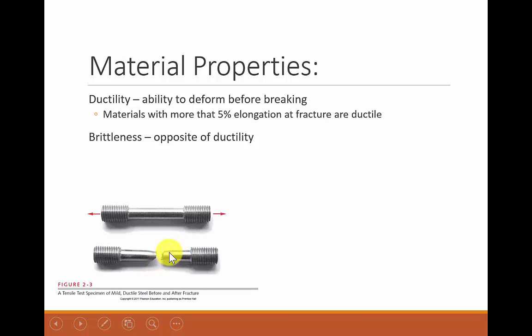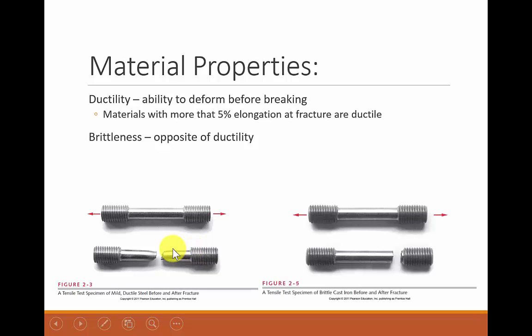They appear to fracture 45 degrees away from the normal stress, which makes us think something about the shear stress might be what actually caused the failure. So here's a good time to remind ourselves that although we're only applying normal stress, the individual elements within the part exhibit not just normal stress but also shear stress in the 45-degree plane away from the normal stress.